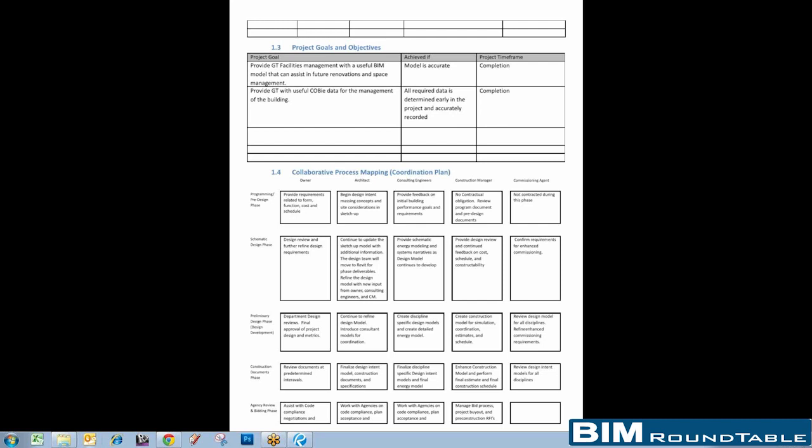It's very important that the mechanical design is followed. It's an intent, and a lot of work goes into the calculations of how to maintain the climate inside a space. So if we specify a VAV box with so many horsepower generating so many BTUs and letting loose so many CFMs into a zone, that's what needs to go in.